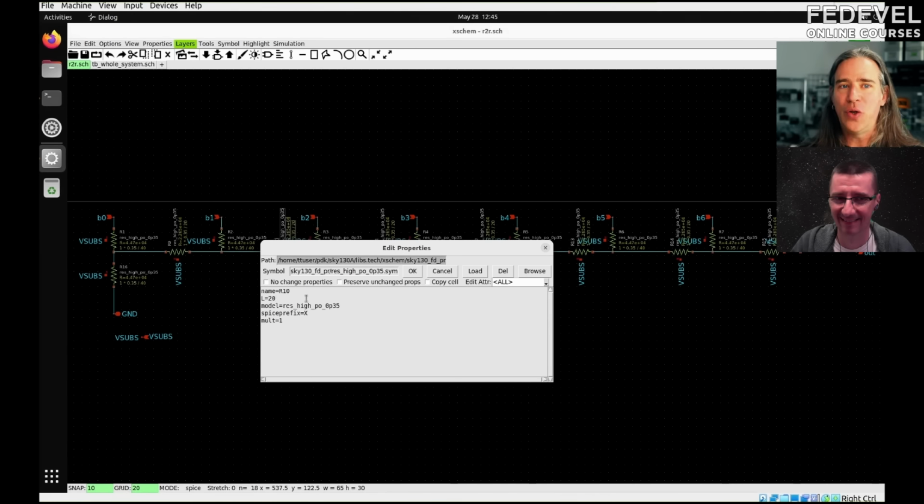So what you should do is have 1 resistor, exactly 1. And then if you want 2 times the resistance, put 2 of those. Because in theory, 2 times longer is 2 times the resistance. But in practice, the smaller you get, the more everything counts, and those little connectors count. And so you start drifting from the 2x you wanted.